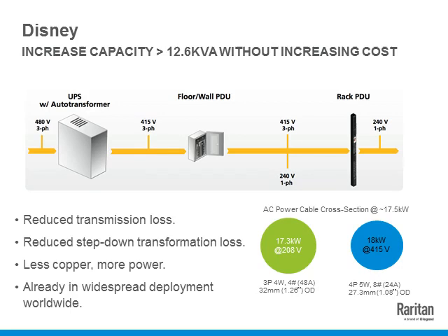It's pretty bulky. If you want to do the same thing at 415 volts, you can get away with an 8-gauge wire. So that's quite some savings in copper, and thereby the outer diameter of the inlet cord itself is smaller. So that's the savings on the copper side.